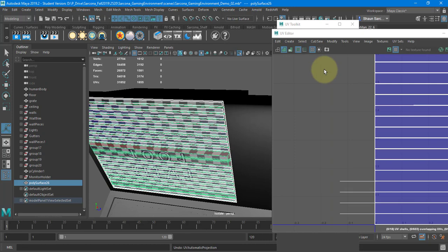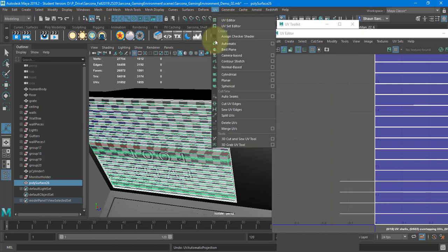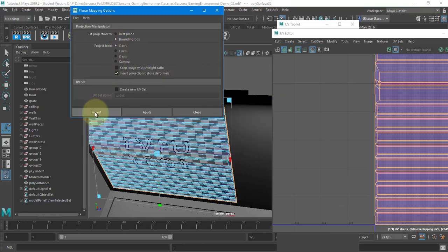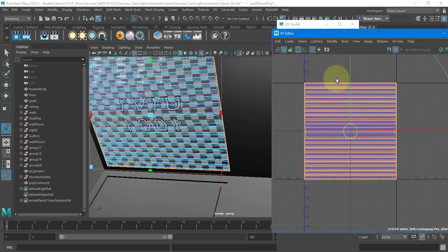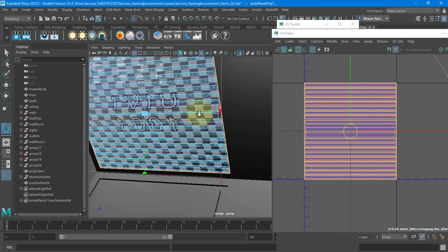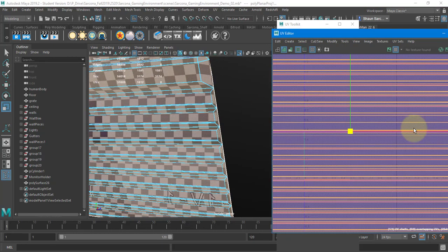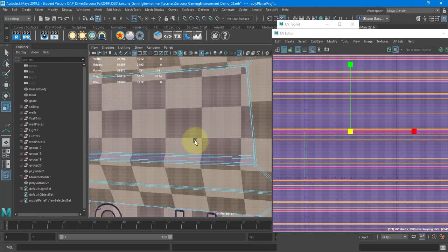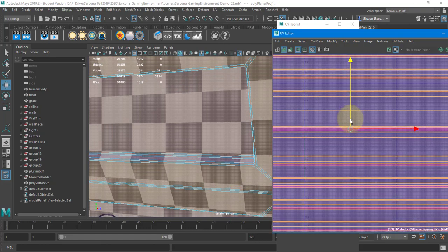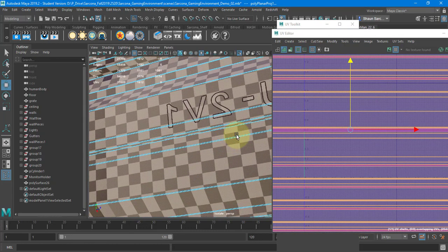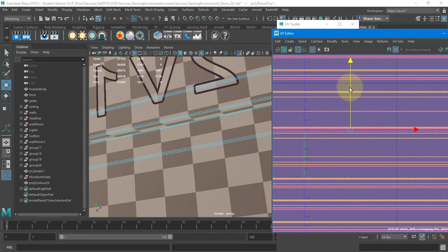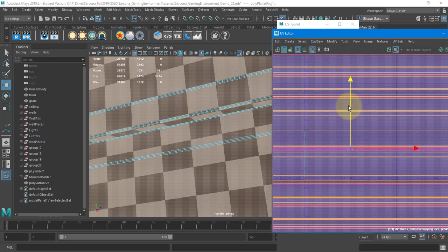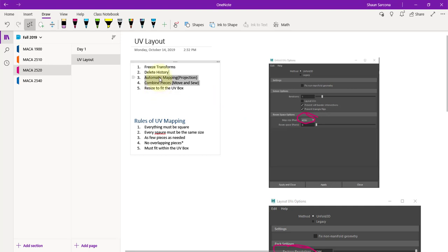Like I said, we start with automatic, see what it gives us. Doesn't give us good results, then we switch. So in this case, I'm going to do planar mapping, okay? Cylinder, planar, or spherical. I don't think I've ever used spherical. Typically, I'm going to use planar or cylinder, and I'm going to just use planar on this. And I'm going to pick the X direction and planar. Okay? So that gave me this, which is pretty close to what I would need. Now, I can't really see it, but if I were to scale this up huge, when I get into some of these tighter areas right here, now it's actually doing a pretty good job there. Let's go this way. Yeah, there it is. So right here you can see how we're kind of stretching and squashing some of those things. Okay? So in this case, I didn't end up using automatic mapping.